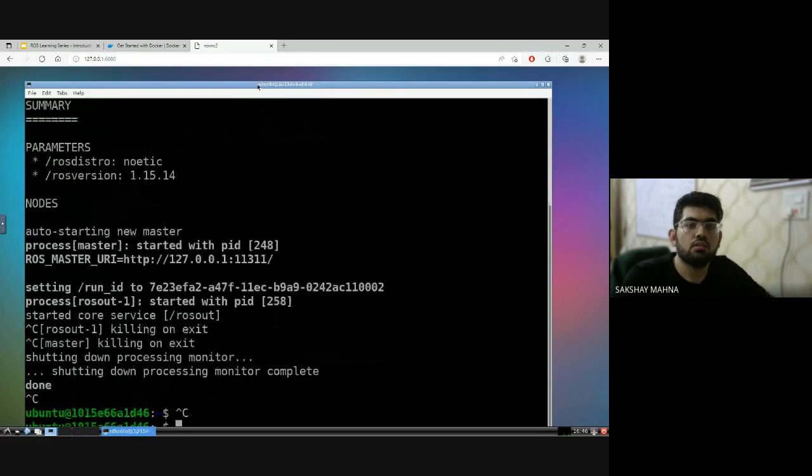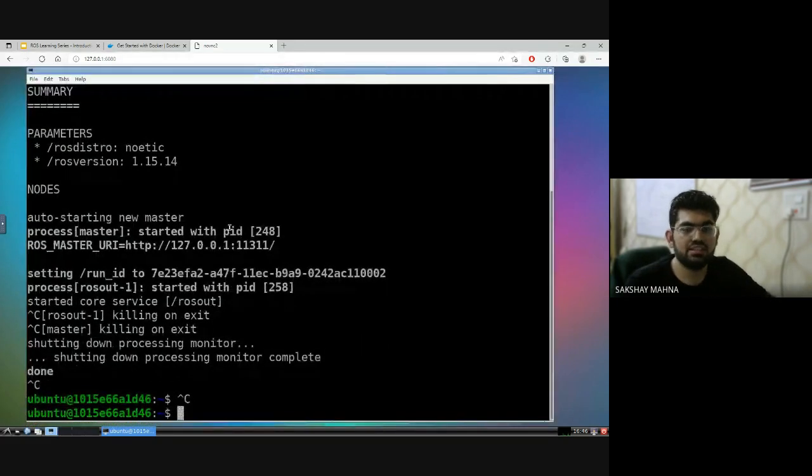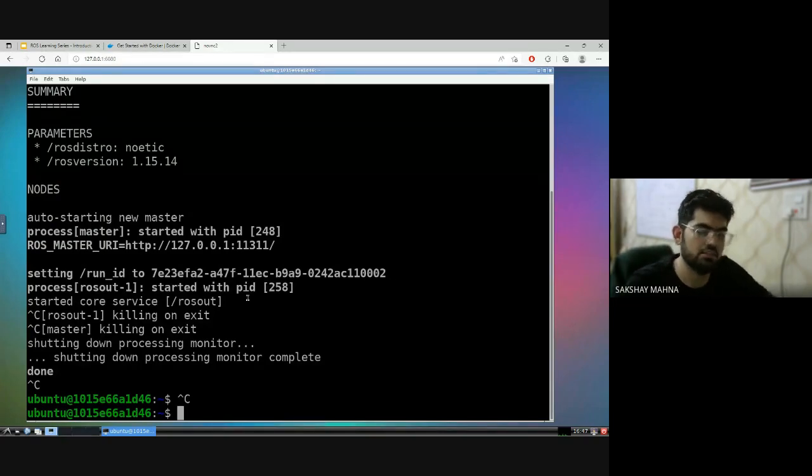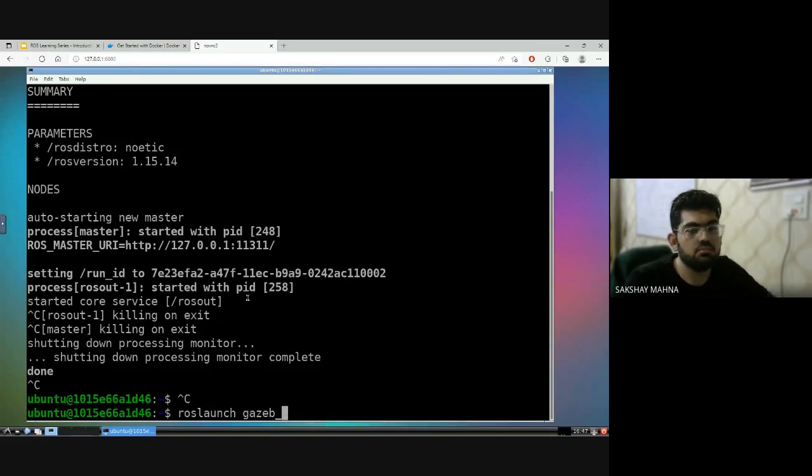Okay, so for today's session, we are only going to run a small demo. The first thing that we are going to run is the Gazebo simulator. Now the commands that I will be typing over here, you do not need to completely understand what we are typing. Just follow these and you may get the results that we have. We are going to discuss what these commands actually mean in the next sessions. So the first command that we have is roslaunch gazebo_ros empty_world.launch.